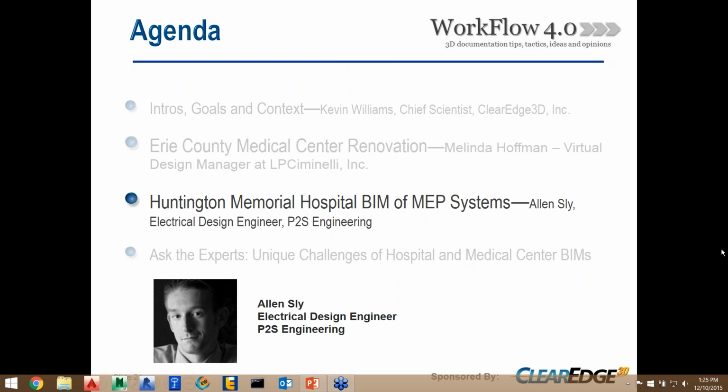First one: does the scanning and modeling include both the structural components as well as mechanical and electrical equipment? No, we only modeled the MEP systems, and just the MEP systems that we needed. For electrical equipment, I didn't get too involved with individual conduits. If there was a large rack of conduits, I would just model it as a rectangle to save on time. Okay.